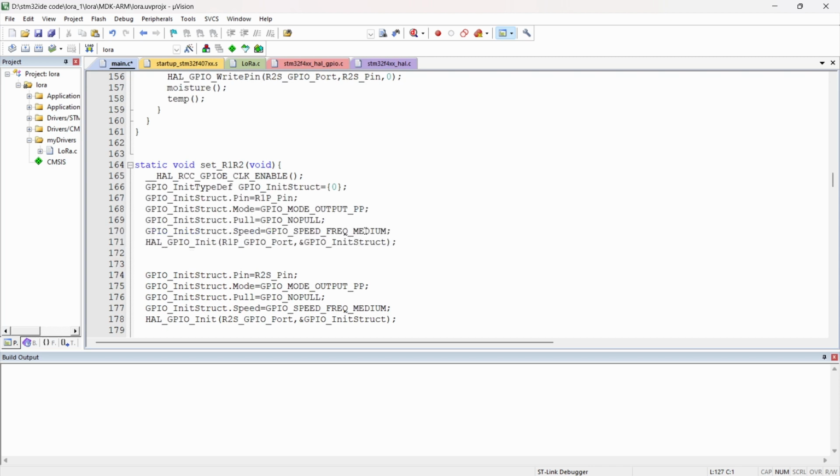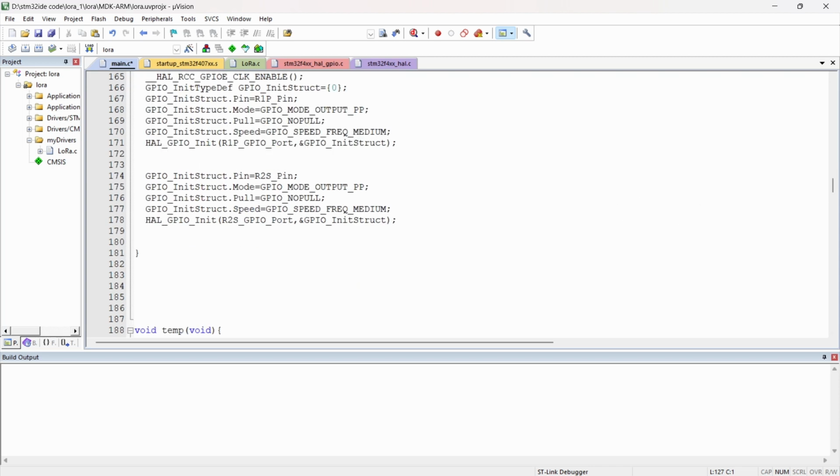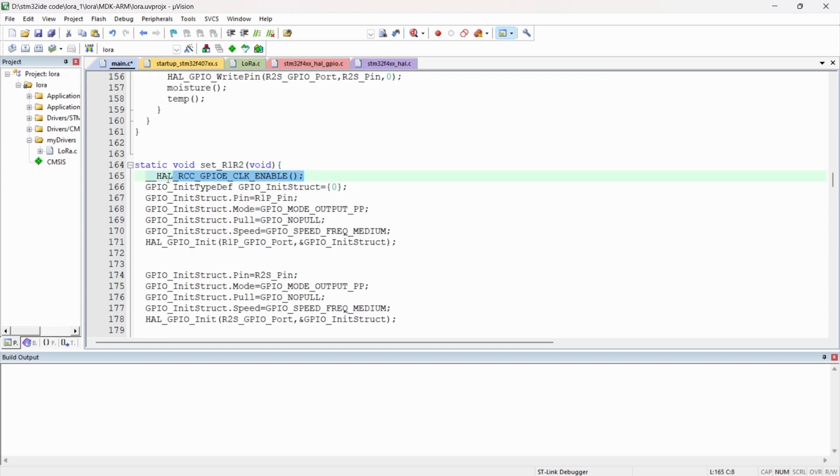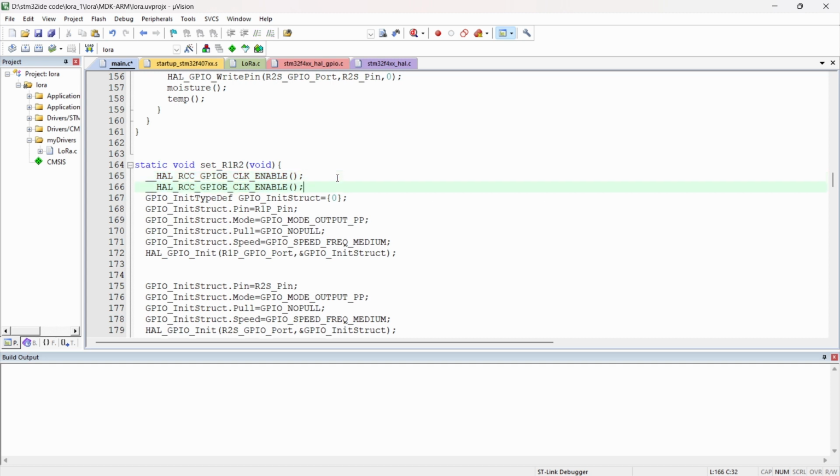So what is the next thing we are going to do is we are going to add the GPIO pin to it because we are going to see this output in the LEDs. Okay. So we have to add some GPIO inputs as outputs. So this port I am going to use is D port because we have this inbuilt LED in the D port. Okay.